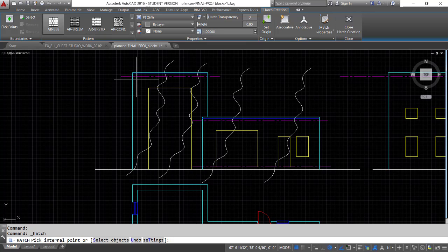I will use a standard brick, because the tall portion of our building here is the standard brick. It looks like it's showing up with the 8 by 8, which is not what I want, but I'm going to click on the brick standard and hover over this, and it fills that area in. Notice that it's being stopped by the line that makes up the door opening. If I go in here, it'll fill in there, as long as it's an enclosed area. But also notice what's happening up at the top, that it is being stopped by that structural line, the line that marks the line of the roof.